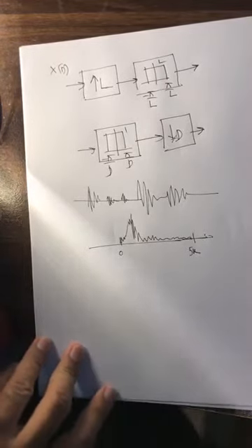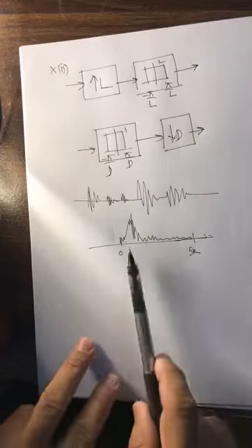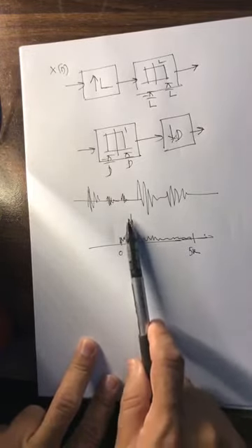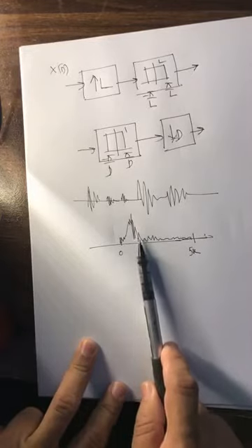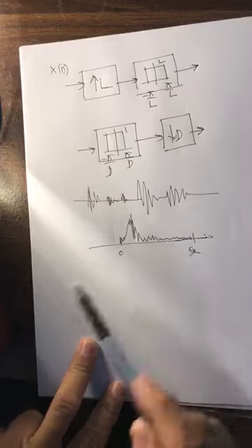Welcome to DSP1 was looking like this, and mostly the voice signal will look like this, that most of the energy will be in this part. There is no DC value, and then most energy is in this part, 1 to 2 kilohertz, and then less energy in this part if it is simple voice.